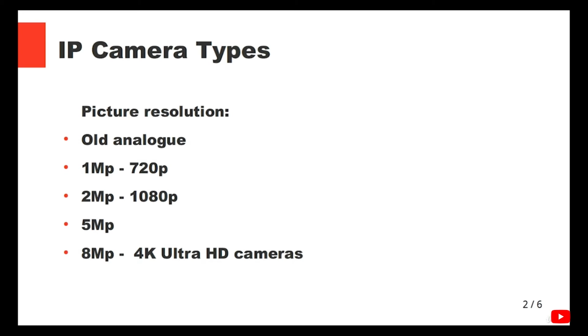And the good thing about IP cameras in the resolution is that you can log into the camera and change the resolution. So you can buy better cameras, let's say they have an older NVR which cannot handle more than 2 megapixels. First, because you can stream them somewhere else individually, and also because you can one day upgrade your NVR.